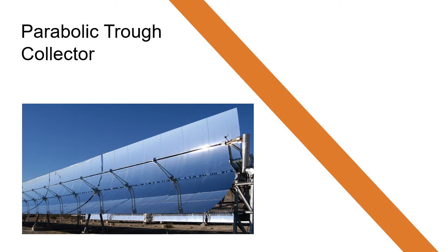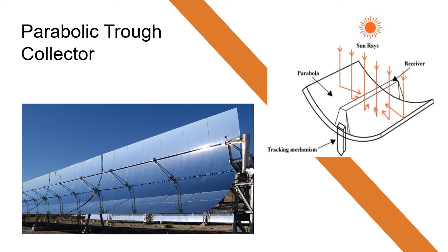A parabolic trough collector, or PTC, is a linear focus solar collector. It is basically composed of a parabolic trough-shaped concentrator that reflects direct solar radiation onto a receiver tube located in the focal line of the parabola. The large collector's aperture area concentrates reflected solar radiation onto a smaller surface of the receiver tube, heating the fluid that circulates through it. Typically, rows of parabolic mirrors are mounted in parallel on either a north-south or east-west axis